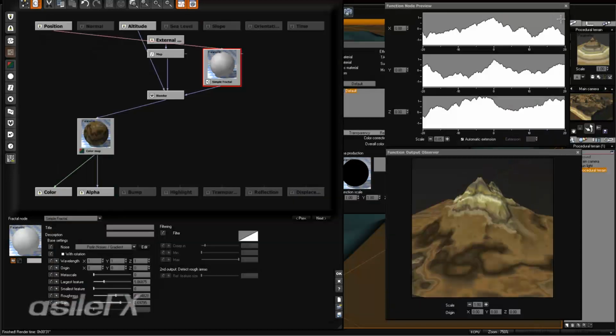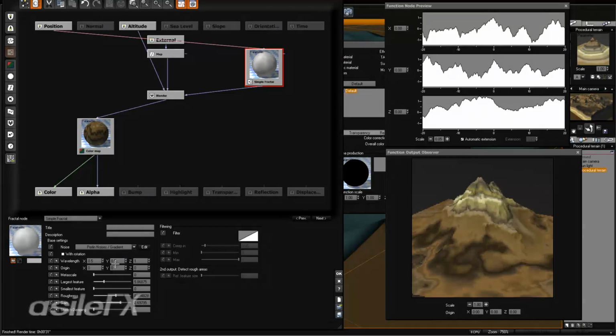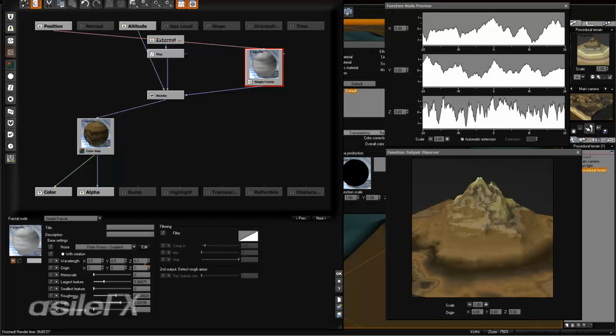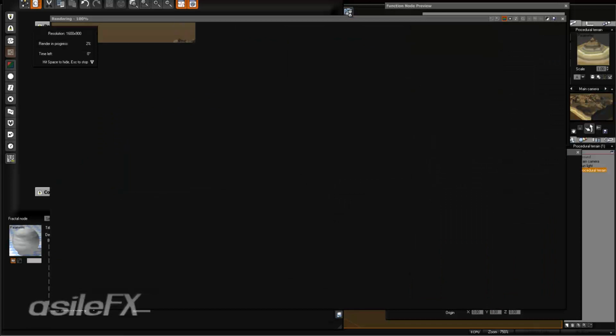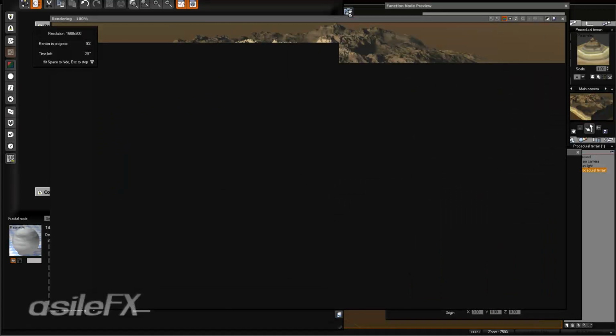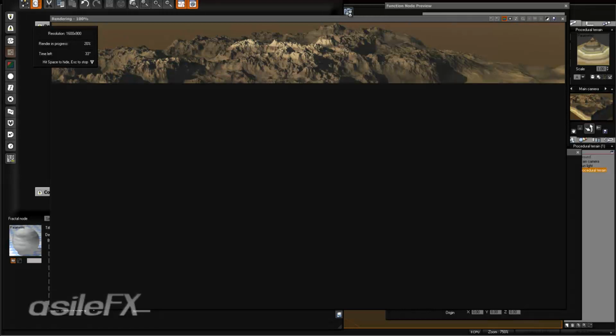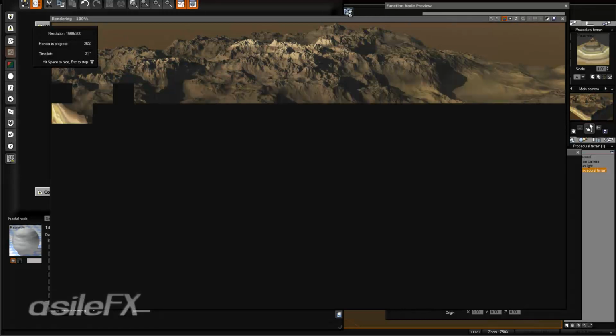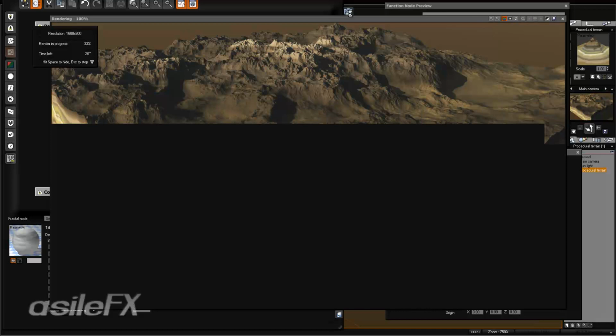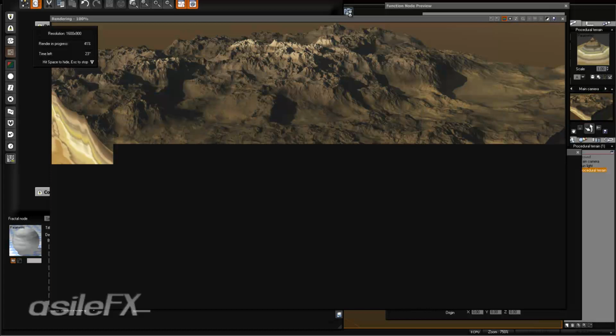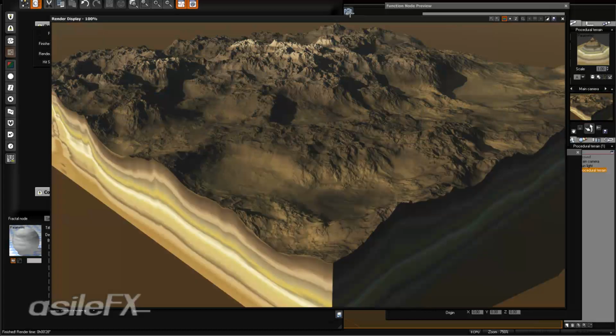So what I want to do is reduce the scale of the fractal. I'm going to set the wavelength to 0.5 on the X and Y and set the Z to 0.1, because we're mostly going to need that Z information to cut this out. And since our terrain is very squished and we're in a parametric mode, reducing that value even more is going to already create sort of a layered effect that we can use. So our variations are getting a little more extreme.